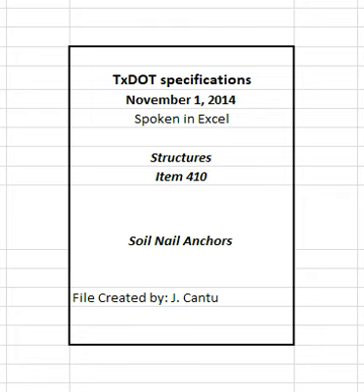Insert the epoxy-coated bar with the centralizers attached and fill any void that is left from the insertion of the bar. Fill the hole completely to the face of the cut. If caving or sloughing of the hole occurs that prevents open hole grouting, furnish either hollow stem auger equipment, placing the nail reinforcing bar and grout through the auger, or casing to support the sides of the excavation. Use grouting methods that result in complete filling of the hole at the ground surface. Methods may include placement of grout in multiple stages or other approved methods. Completely remove any device used to dam the front of the hole immediately after the grout takes an initial set.